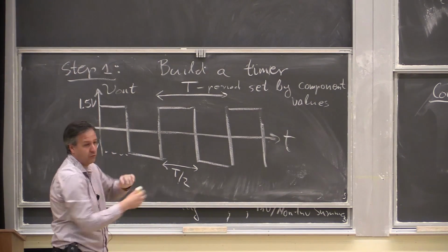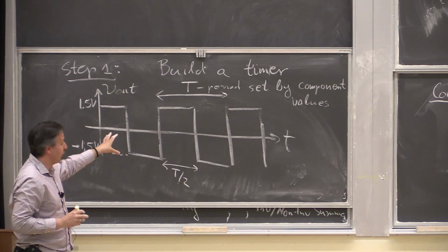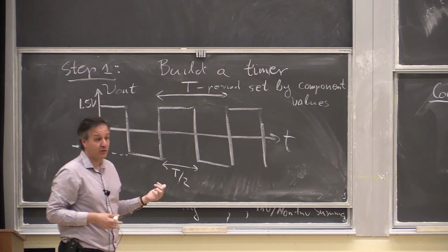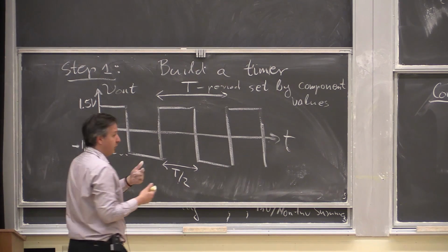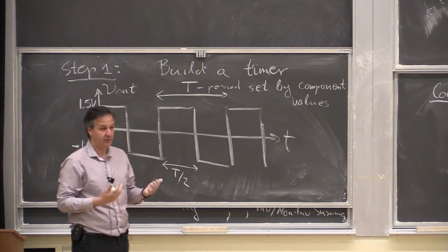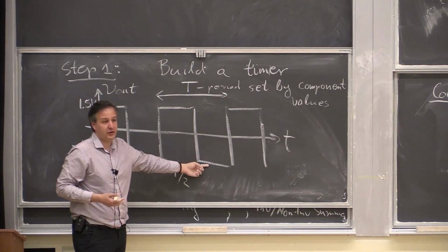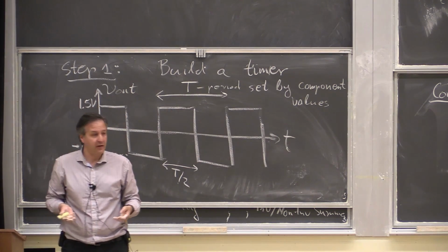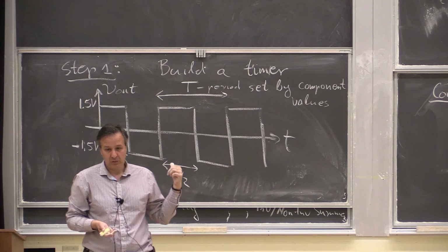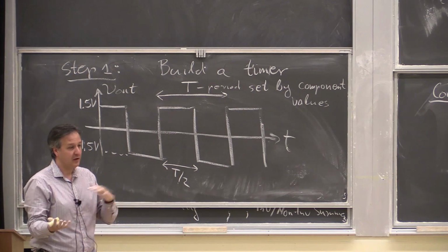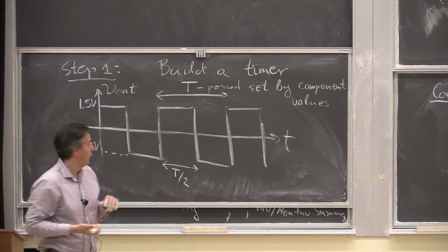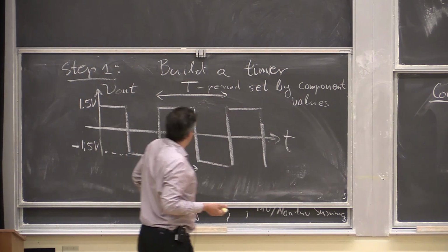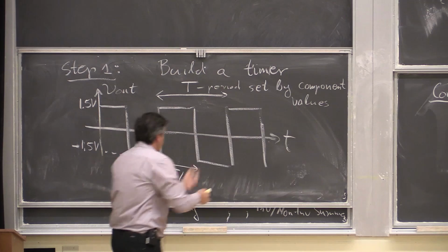There are many other control systems where you need this sense of time. Even when we did the D to A converter example, there was something that had to switch the switches. Well, this can switch the switches. Phase 1, phase 2, in our capacitive sharing thing. I can use this to do the charge sharing. So many uses for this type of timing source. So okay, let's see how to build it.